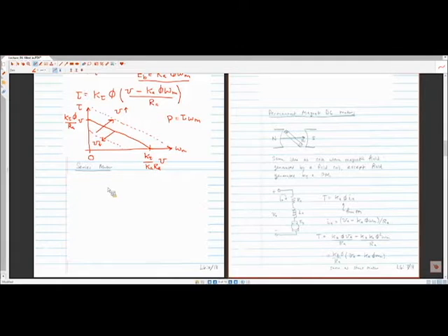They don't really differ in the actual physical hardware you build, but you wire up the circuit differently. Instead of having a field circuit and armature circuit in parallel, as the name suggests, the two circuits are in series.